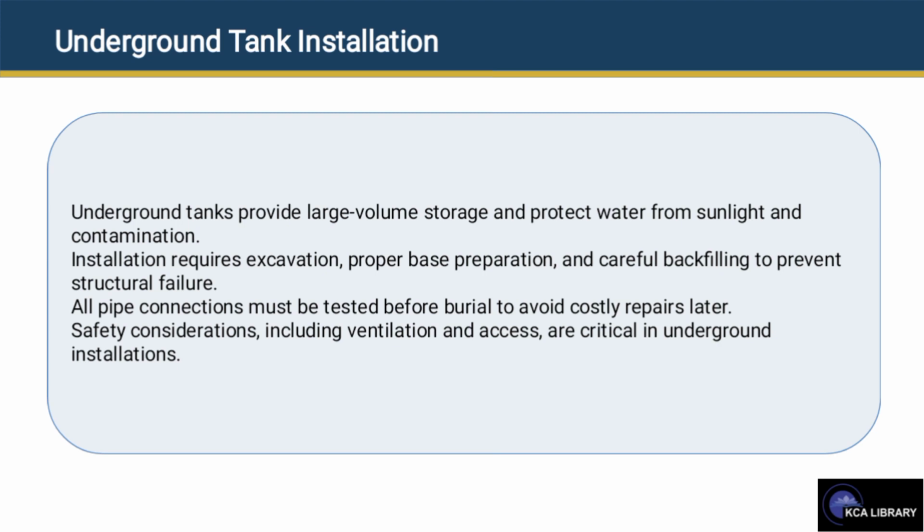Underground tanks provide large volume storage and protect water from sunlight and contamination. Installation requires excavation, proper base preparation, and careful backfilling to prevent structural failure. All pipe connections must be tested before burial to avoid costly repairs later. Safety considerations, including ventilation access, are critical in underground installations.